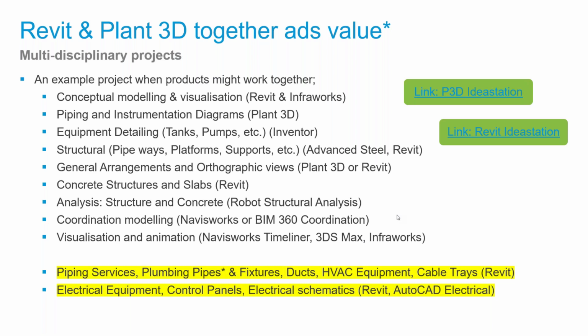Yeah, some comments here on the coordination in BIM 360. So, as you know, your live models are in the Project Files area of BIM 360 Docs, but the BIM 360 coordination takes place in the Plans area of BIM 360 Docs.